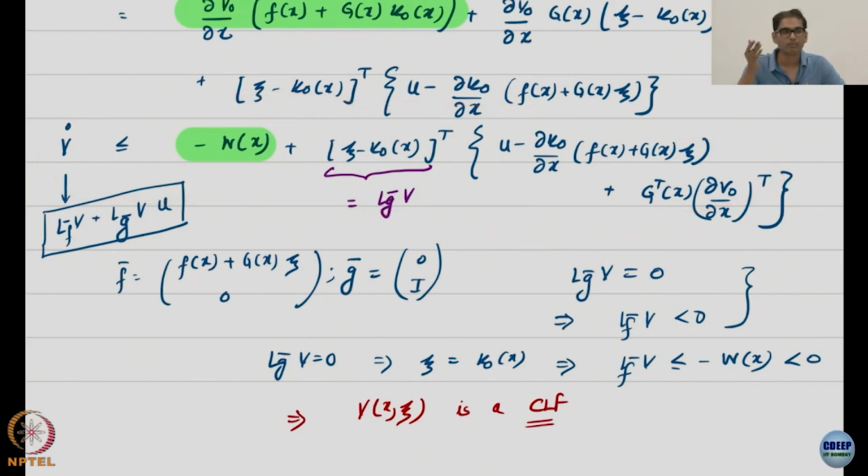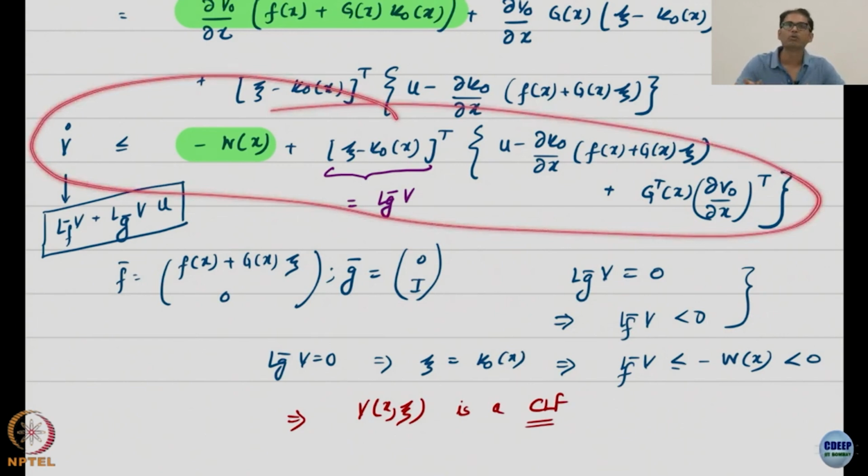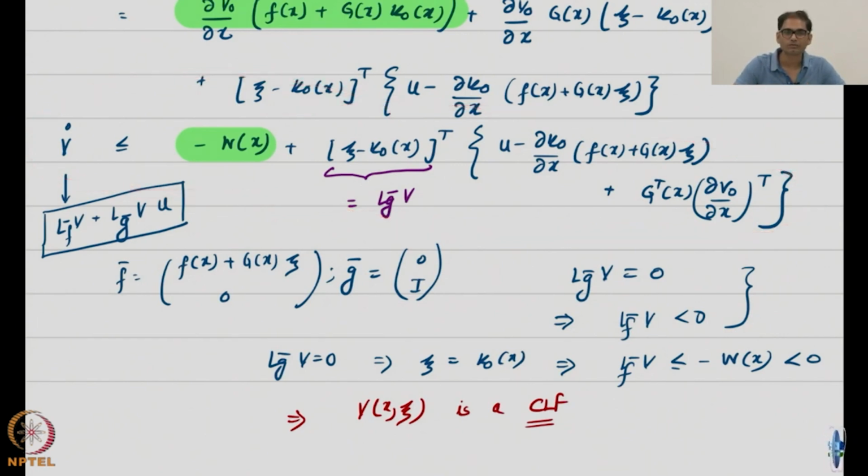You take a Lyapunov function, because a CLF is also a Lyapunov function, right? So you take this V, take the derivative and try to make the derivative negative definite. You said it's a CLF, excellent, and you can use the Sontag universal formula, obviously, that's one choice. But suppose I ask you, just look at this and tell me what is a stabilizing controller.